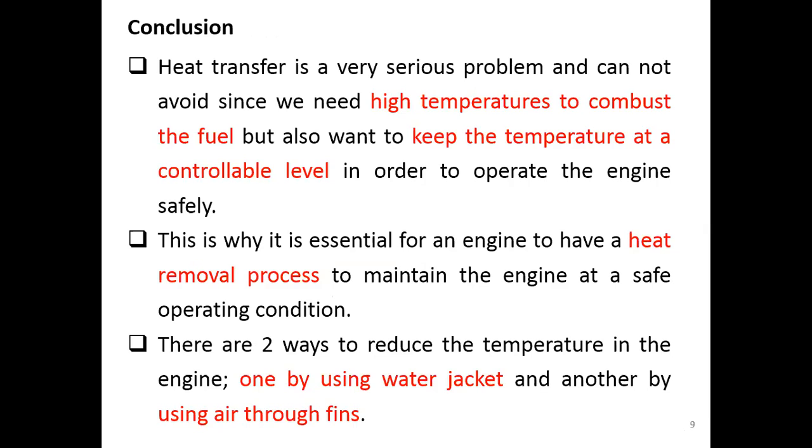We have to face it. It happens always, right? Because we need a high temperature to combust the fuel. Our need for high temperature forces us to have heat transfer that we cannot avoid. And also because we want to keep the temperatures at a controllable level in order to operate the engine safely, we cannot have zero heat transfer.